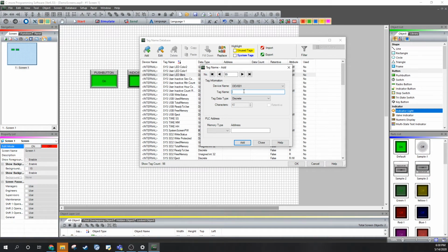The other thing is, I think it's generally probably best practice not to internally reference external memory, or memory that's also externally accessed. You would want to look at the status of something in the PLC that's being changed by a tag on this HMI, and not so much reference that tag both internally and externally, if that makes any sense. I'm getting off in the weeds and probably talking a little bit out of school about things that I'm not really an expert on. So feel free to disregard what I just said.